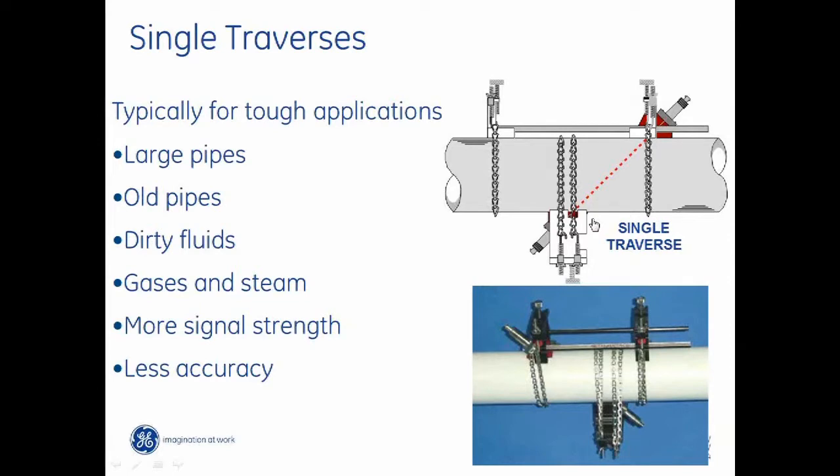Mentioning the outside of the pipe, if you have bubbled up paint or loose rusty areas of the pipe, we don't need to get down to bare metal. You don't have to sand that thing down until you see this nice shiny pipe, but we do need a nice smooth area without any air entrapped underneath bubbled area. So if you take a small wire brush to it and clean off the area, that is 9 times out of 10 more than enough for us.